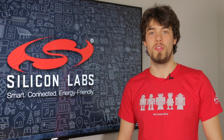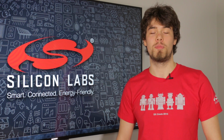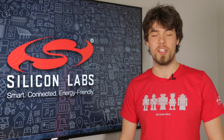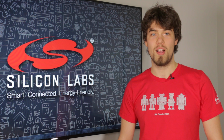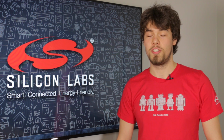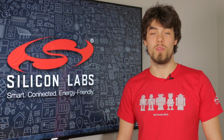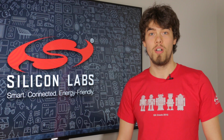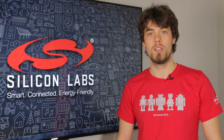Today I'm going to introduce you to mbed low-power APIs, which were developed in close collaboration with ARM. The mbed low-power APIs will enable your application to automatically get into the lowest power consumption mode possible by selecting the best sleep mode for you and introducing an asynchronous programming concept, which will allow you to do background input-output operations while sleeping the core or doing different tasks at the same time.